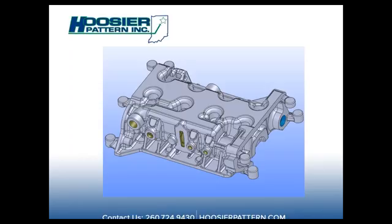For all those castings that are difficult to do, to get a gentle fill and get all your risers, runners, sleeves, filters, all those added things that you want to put in a mold, even chills can be added. Venting also takes on a new perspective in this, because you can put a vent anywhere in the mold, any way, any shape.